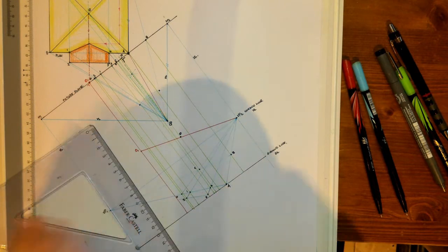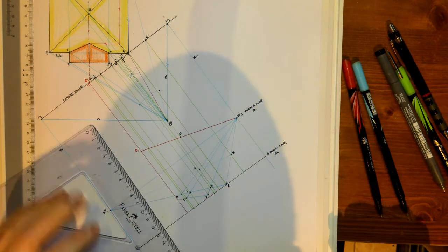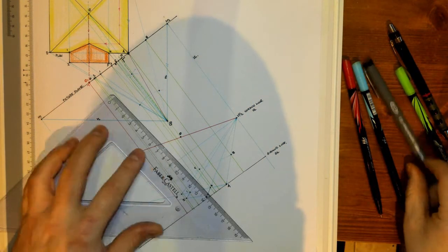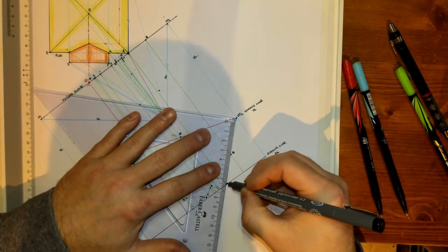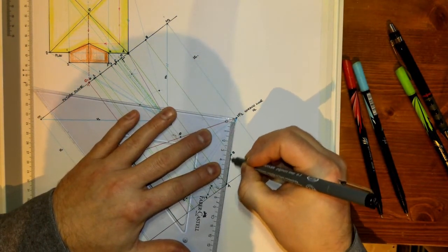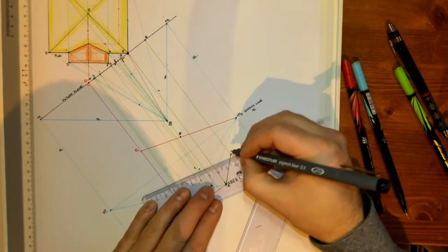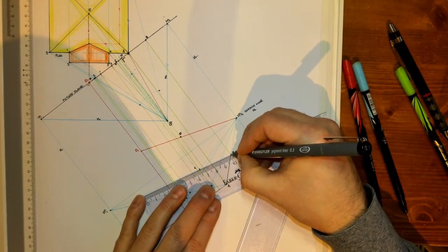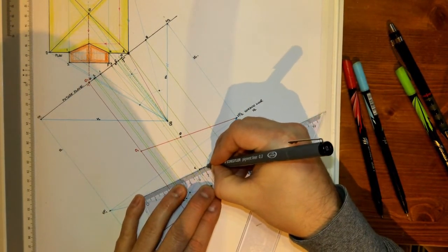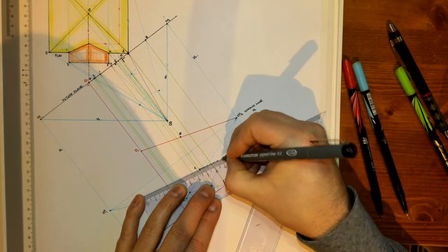Now what I can do is I can draw in most of the structure as follows. Okay, so I'm going to heavy in my line A to B on the ground, like so. That line P to C, that's out at the back. You could leave it out, but sure, we'll draw it in as a hidden detail line.